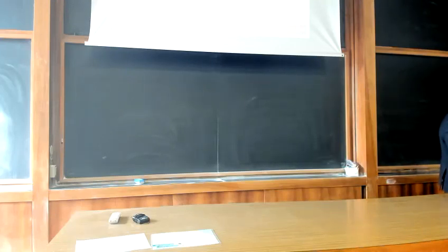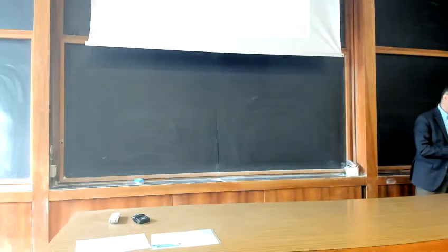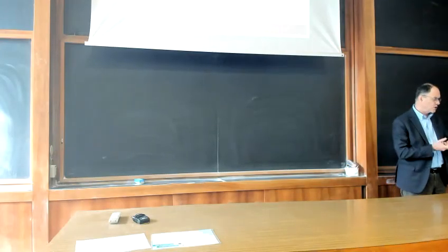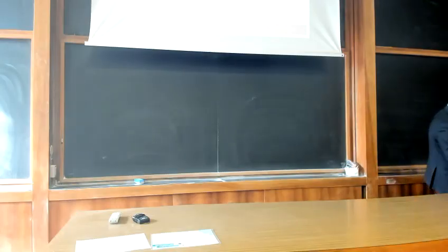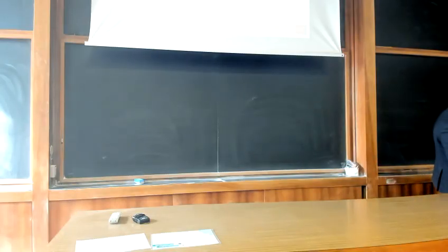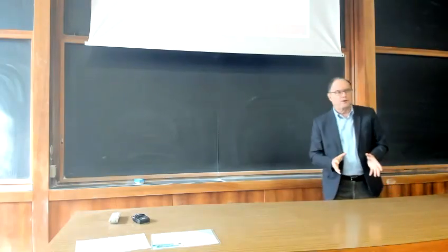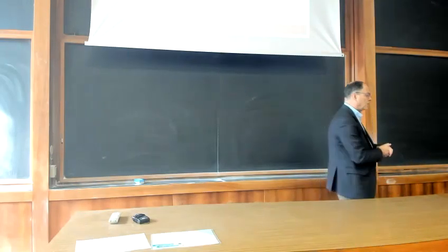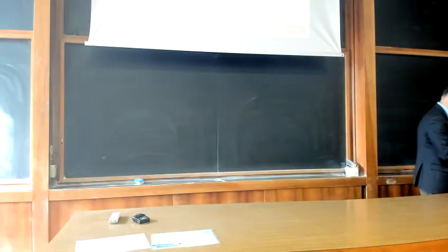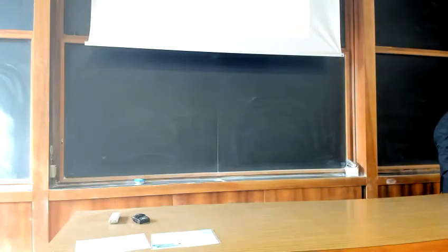Now, this is just a reminder of what happens in undrained conditions. No change of water content, total stress analysis, and you can express the failure criterion of your soil in terms of the Tresca expression. So you have this.